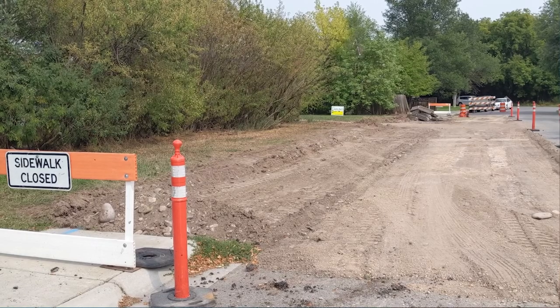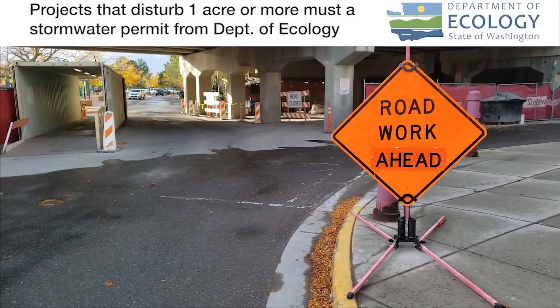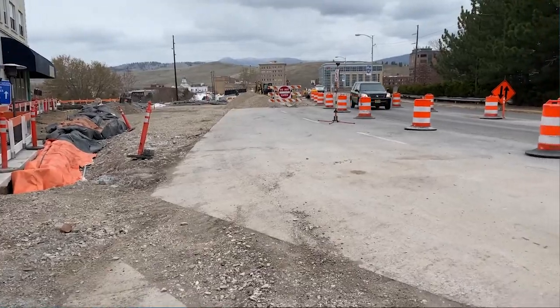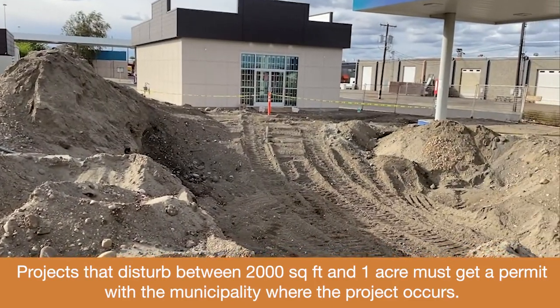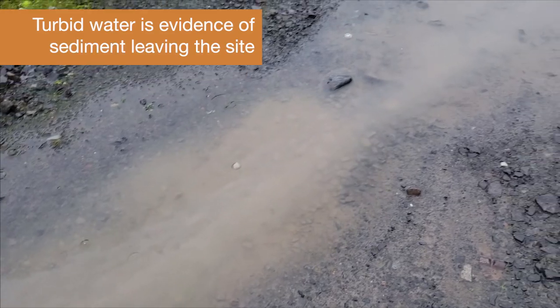Erosion and sediment control for projects that are 1 acre or larger are required to have a permit from the state, but we're going to talk about those projects that are under that threshold or maybe linear or shorter in duration, and we're going to talk about basic principles and management techniques to prevent erosion, prevent highly turbid water coming off, or having processed water commingle into your system.